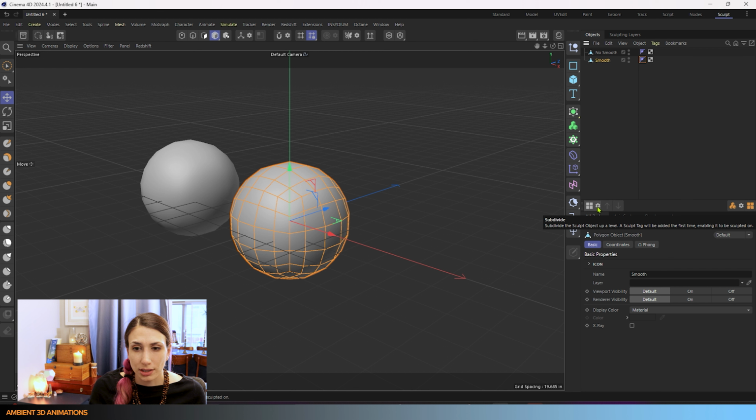So let's talk about the options for the Subdivide. As you may be familiar, if you see an icon that comes with a gear next to it, that's because this tool comes with additional settings. So let's click on the gear to see what those settings are. The setting we have here is smoothness. Now you can adjust how much this is smoothed out as it's subdivided, and I'll show you what that means. I'm going to increase the smoothness to 100%. And I'll click OK.